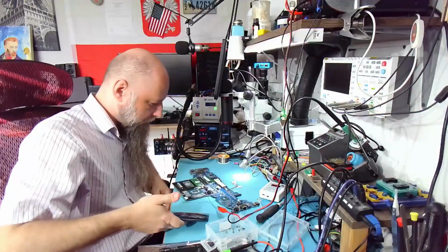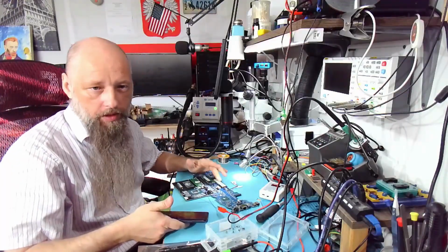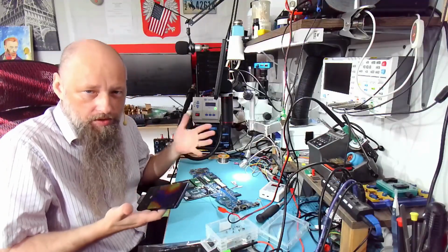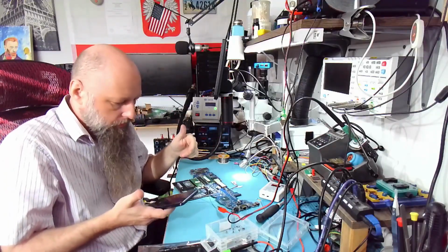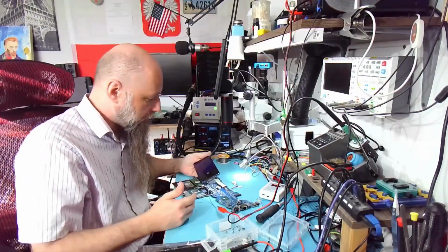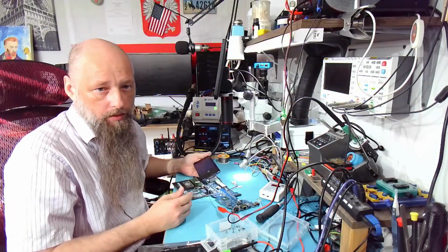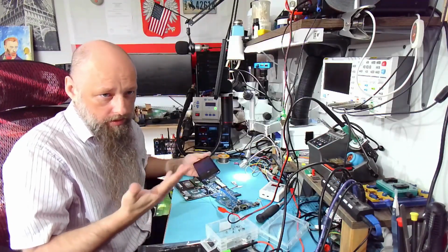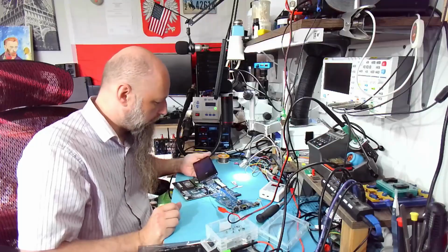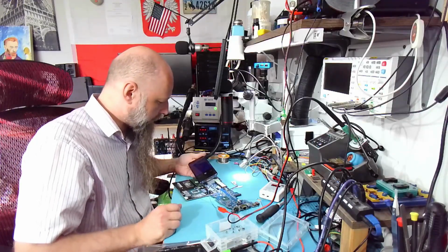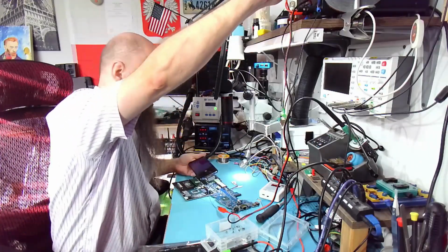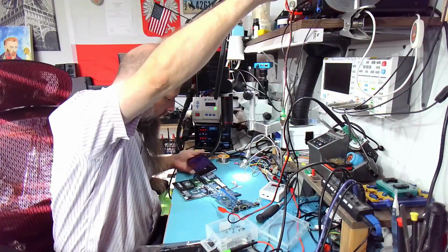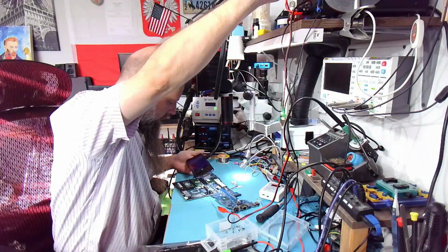That's weird because neither the core nor the VRM lights up. So that tells me that it's most likely a VRM or something else. It's unlikely to be the core because we would see the core lighting up. This is 400 milliwatts that we're injecting. That isn't enough to break anything, but it is enough to see the thermal image. But none of the VRMs are lighting up. So I'm going to check the other side of the board in a second. But before I do, let's check it one more time.